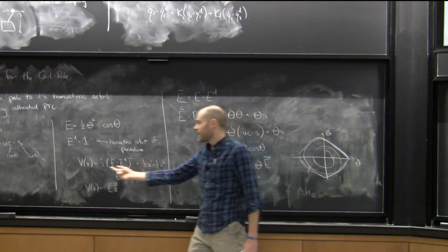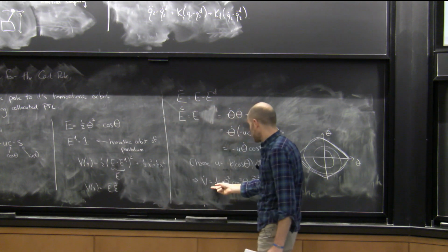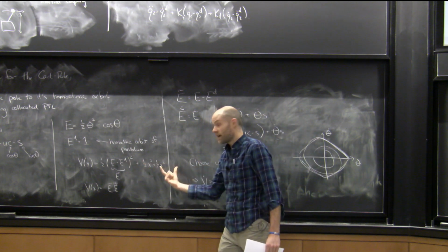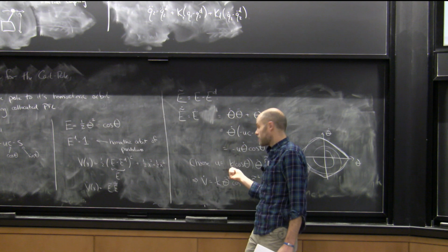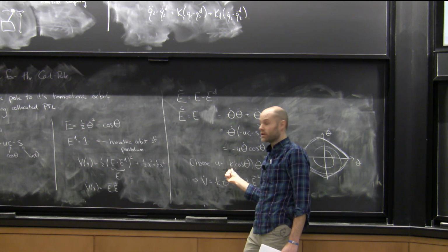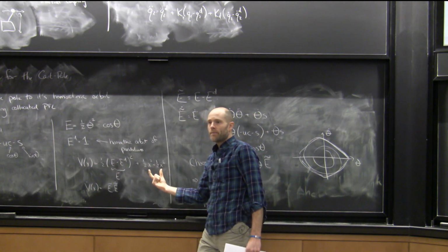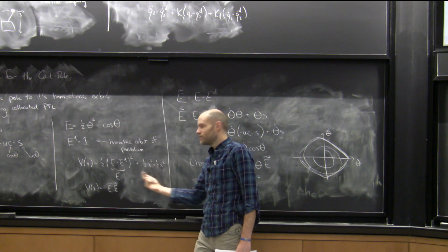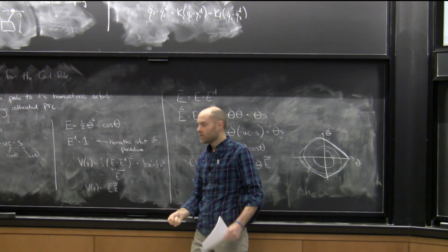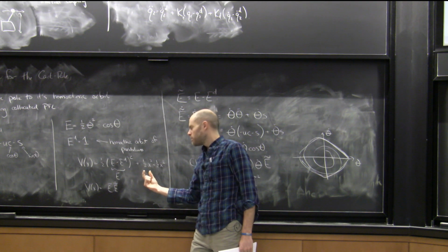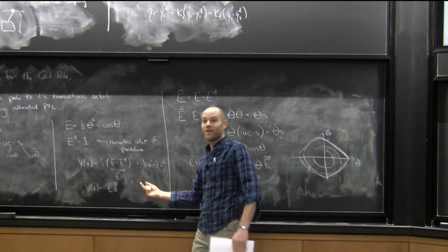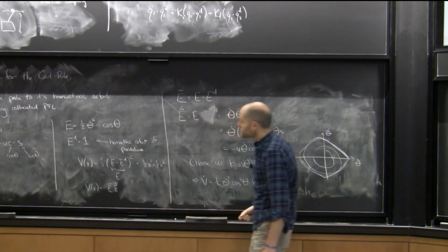Even more so, these are not going to be global controllers. There are going to be some values of k that work. Once I put those coupling terms in, and they do start fighting, in our simple case for just the pendulum, for any k that was positive, we achieved success. I always went downhill. But now that I have these terms fighting, there's actually only a subset of k's, k1, k2, k3, for which those coupling terms fight each other appropriately and you still go downhill. Lyapunov will tell you all of that. It's more algebra than I want to do on the board, but it's straightforward, almost just square everything and put it to work, okay?